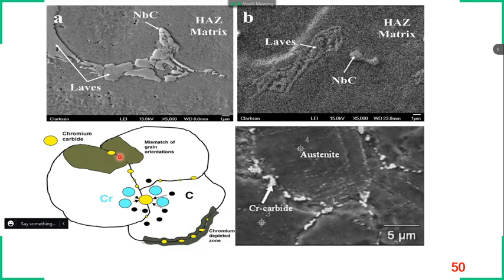Whereas in stainless steel, sensitization is one of the most common problems. Okay, sensitization means the formation of chromium carbide, Cr23C6 or M23C6. That is the most common intermetallic which can get formed in stainless steel 316. As carbon is there, carbon has very high affinity with chromium. It will tend to form chromium carbide at elevated temperature, especially during slow solidification. Carbon can interact with the chromium and tend to form chromium carbide.